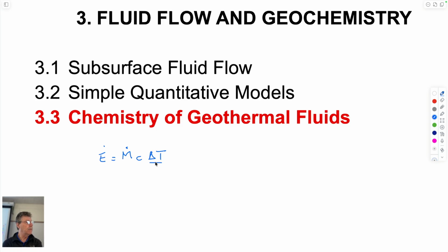When they went into the cold fractures, they would solidify and stop flow into those fractures. And then as the temperature of those fractures came up again, rebounded, because now the heat that was trapped in the rock had a gradient towards the fracture, but now you've shut off the fracture by no fluid going in it. It would build up temperatures next to the fracture.